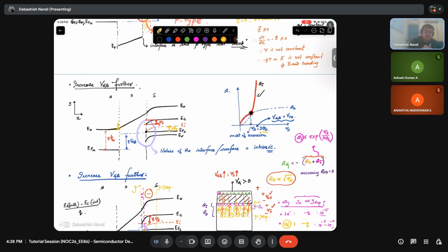So surface potential equal to bulk potential will be at this case where my device is intrinsic, right? In this case, if you see, your EC is coming like this, so this is your surface potential, Q psi S. Similarly, your EI will follow. If EI follows, the EI band bending will also be the same, because the distance has to be Eg by 2 in all cases.